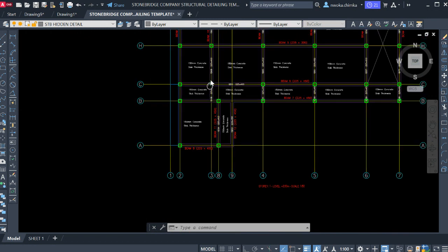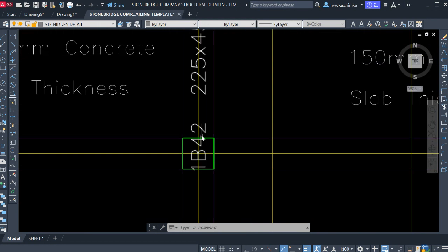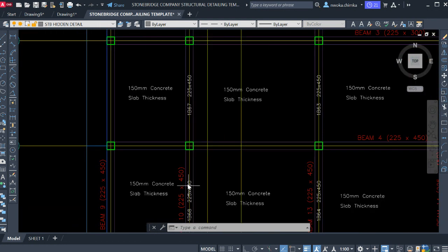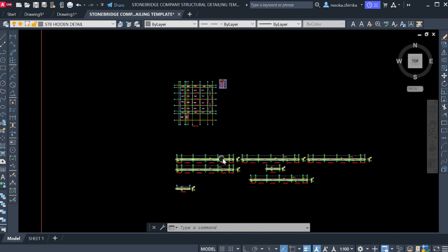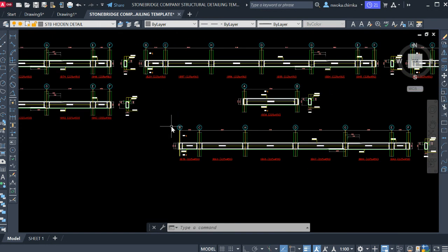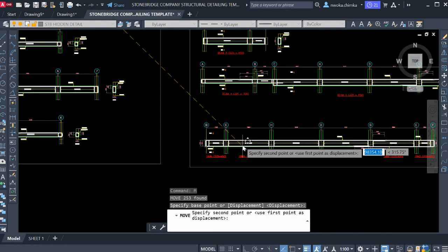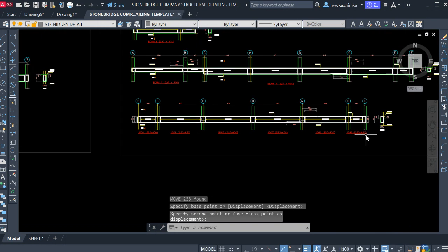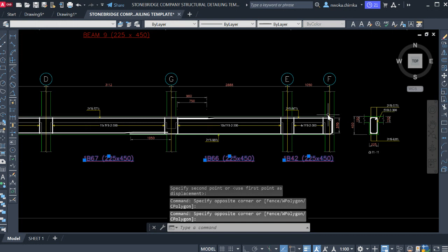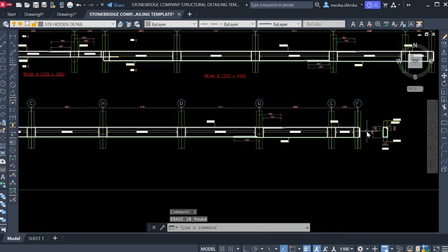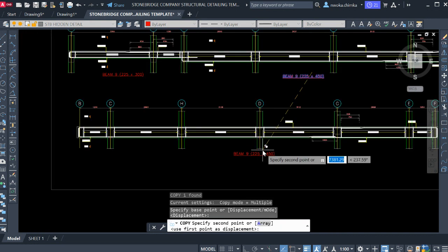So I go now to perform beam 10, and beam 10 starts from beam 36 to beam 42, and it is also a 450 beam. So this is beam 10. So now go and locate beam 36 and call it beam 10. So beam 36, right, this is it right now. So just move this right now to this place, and remove this beam naming that came with Prota Structure, remove this unnecessary dimension that came with it also, remove this, and then name this our master beam as beam 10. So copy this one right now and replace it as beam 10.